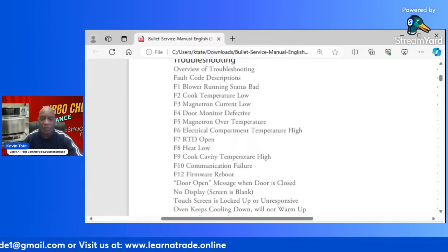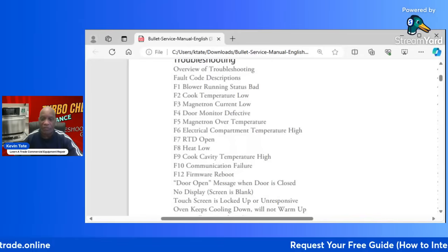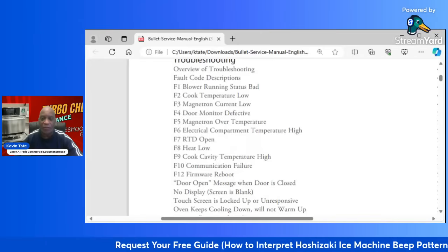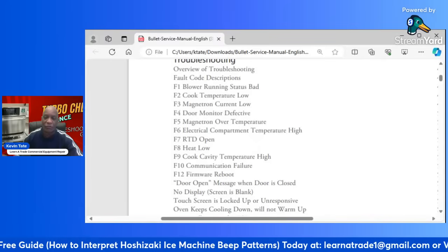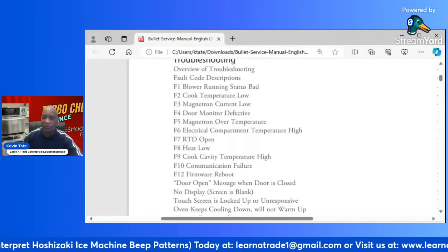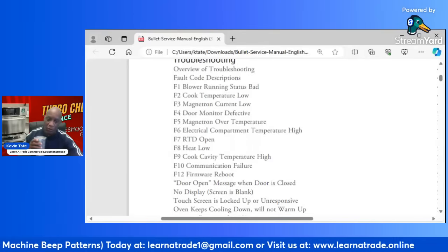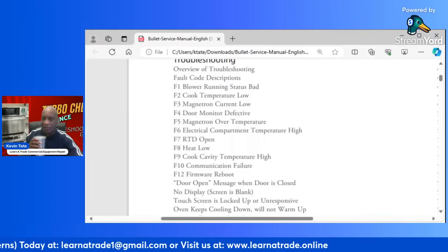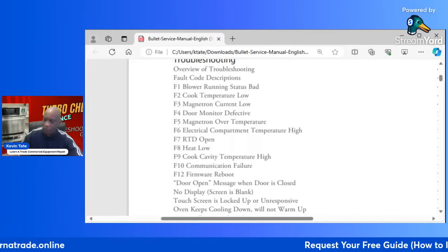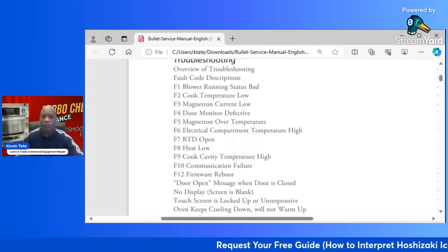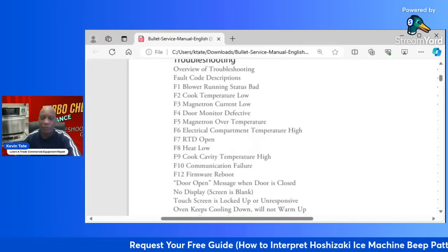So be sure that you unplug that and de-energize your capacitors. On the newer models, they say that the capacitors automatically de-energize once the unit has been shut down, but I always take caution, and I'll de-energize them anyway. But make sure that you unplug that first.